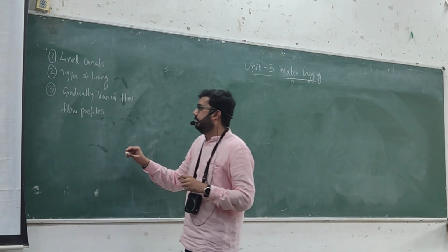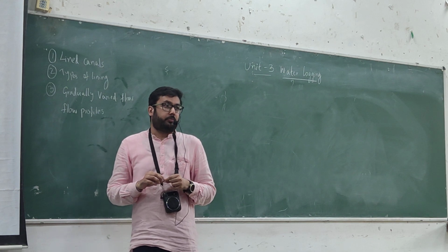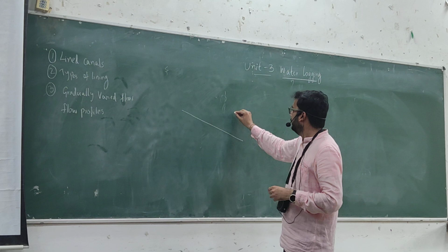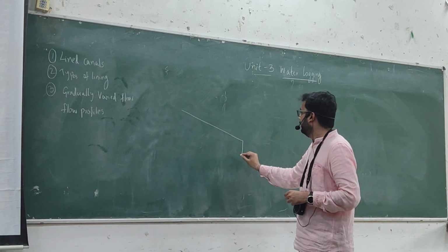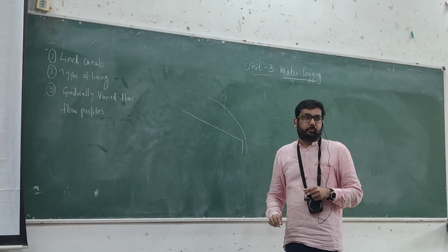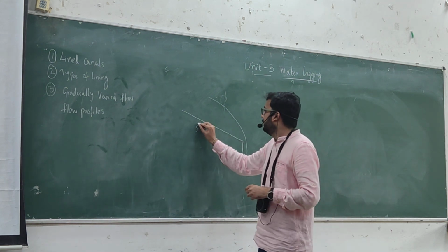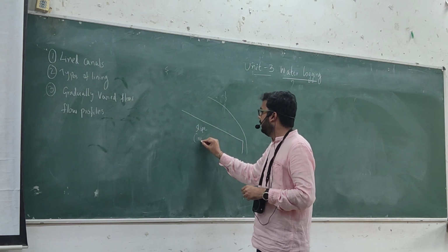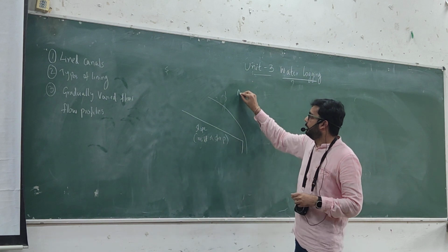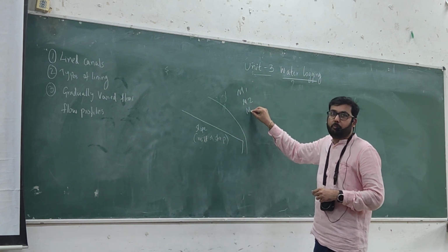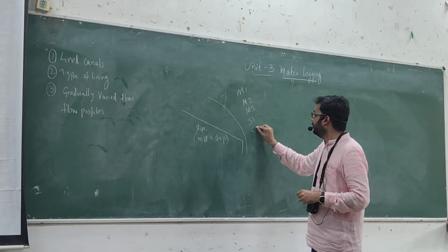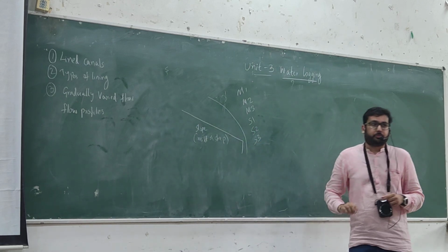Okay. So let's say this is the bed, and then you have a drop. So what kind of flow profile would it be? You can classify based on the slope. So if the slope is mild or steep, then for mild slope we have three types: M1, M2, M3. These are the three different flow profiles. For steep slope, we have S1, S2, S3.